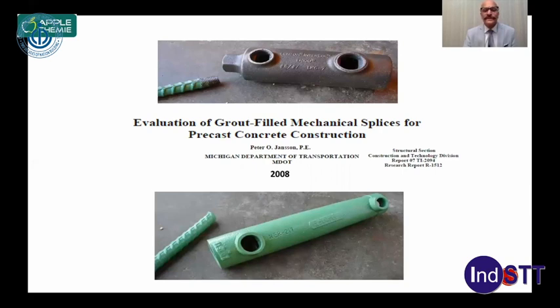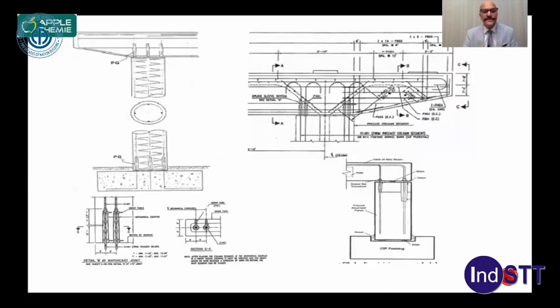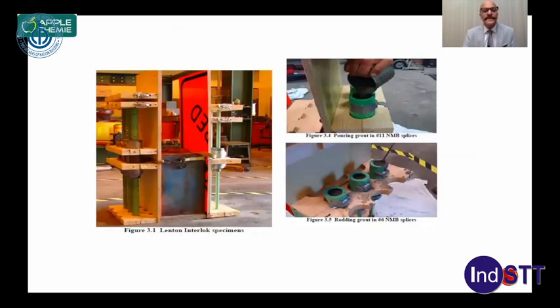This is what I mean by the coupler. These are the couplers and the extending pieces. These are used for the extension and the continuity of the reinforcement. And there are various uses of it. You can use it in infrastructure, like what I have shown over here. This is a huge column and beam connection, or a vertical connection also. These couplers can be tested in the laboratory, and the grouts which are used in the coupler are even more important because the coupler is basically a mechanical thing and it can be tested for various mechanical parameters.